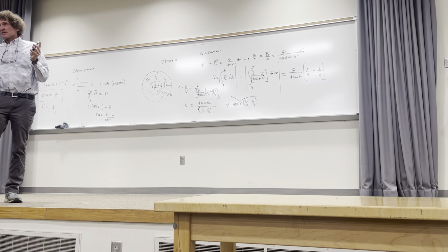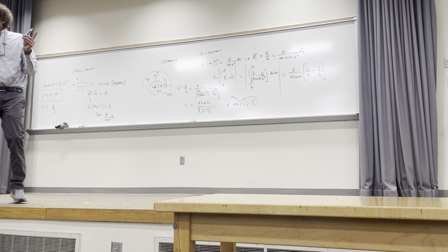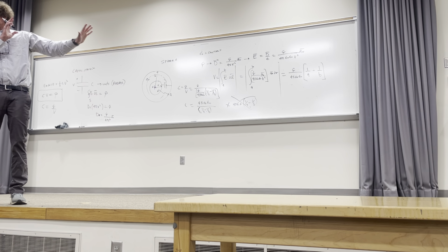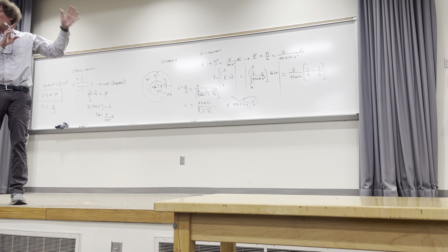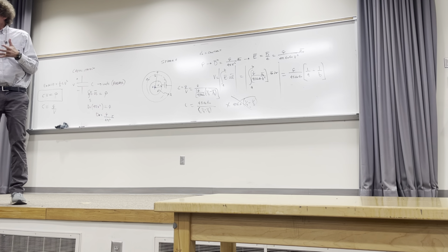Well, I'm not a specialist on this, and I don't want to talk outside my area of expertise, but I can say this. When you're talking about dielectric constants that are near 40, 50,000, typical up to 10 is about the upper limit on most common dielectrics where you have a breakdown strength that's reasonable. Then you're talking about stuff that is beyond standard material science and stuff that I've had. This stuff is exotic, and it probably has to do with materials that are engineered with like carbon nanotube technologies and things like this, and I don't know that, but I'm just going to say this.